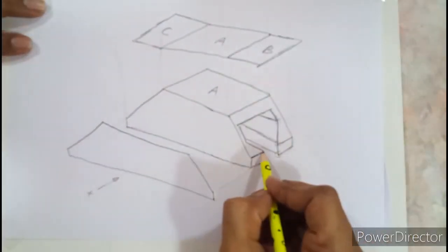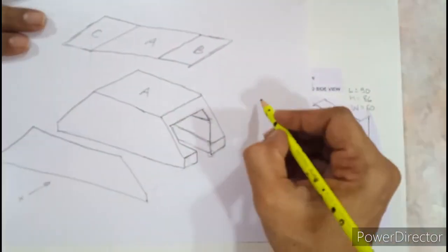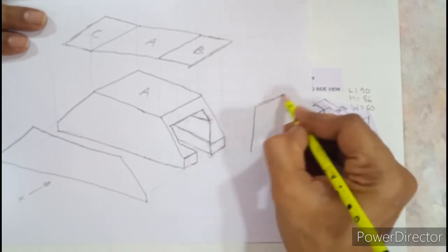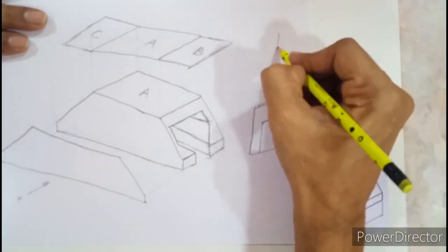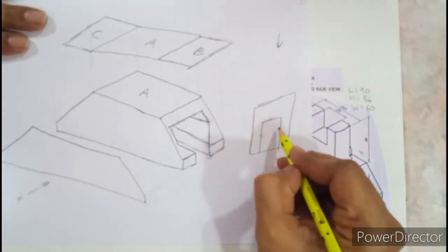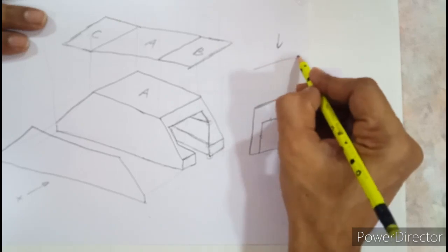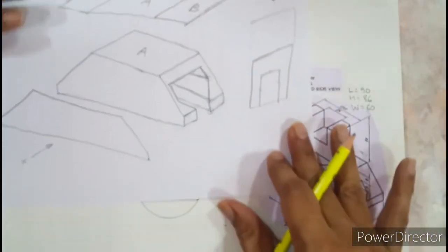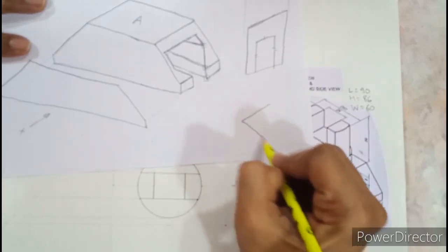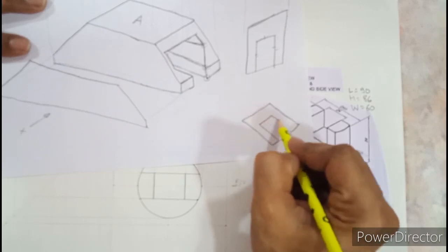Now if you carefully look at these lines, and if you try to analyze what I'm going to show, suppose there is a vertical surface, and if you draw three lines, so in the top view, can you see these three lines? Answer is no, because you can see only one single line, that is the projection of this surface will be seen as a line, isn't it? But suppose the same thing, if I show on an inclined surface, if I draw three lines like this, then what is the top view now?